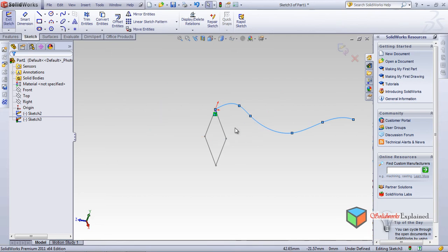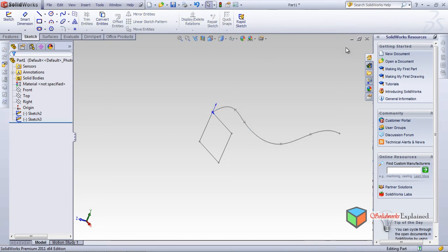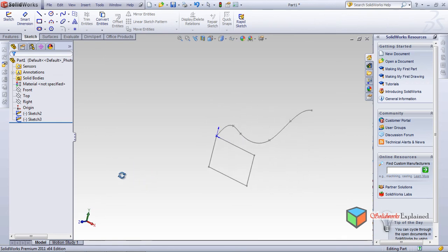Okay, I made this in the right plane. This is a 3D sketch. So this is done, reverse, back. So now you can see two sketches, one sketch and two sketch. Always there should be two sketches, keep in mind. This option is really a troublesome feature in SolidWorks, because it gives variable results every time, and most of the time it gives errors.